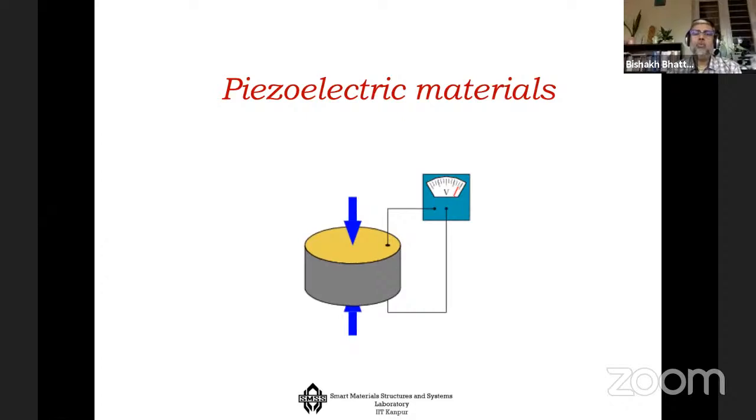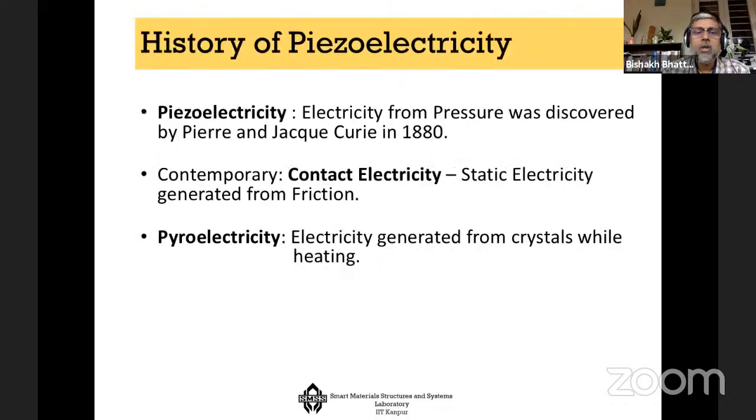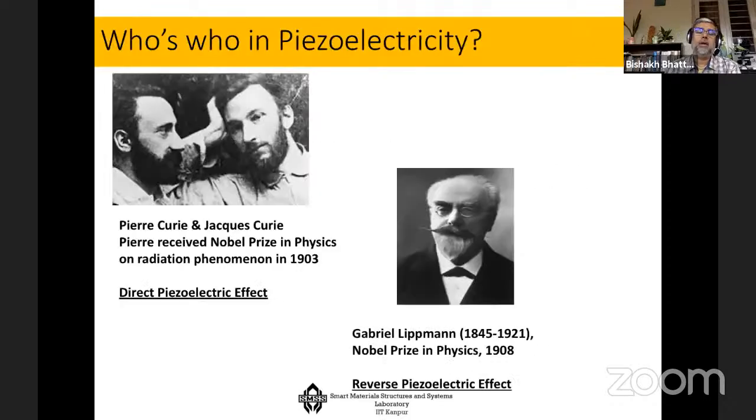Now, one of the first groups of materials in this direction is called piezoelectric material, in which once you apply the voltage, you can see that there is a change in shape. Also, if you apply force, if you expand or contract the material, you can generate voltage from it. So the material can sense as well as actuate. This material was developed long ago, in 1880, but only today are we getting the advanced form of it, which can show the effect in a very predominant manner.